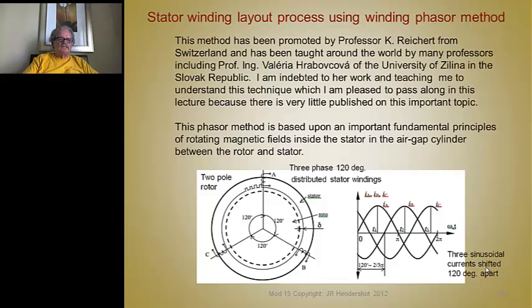I'm really indebted to her work and what she has taught me about how to understand this technique, and I'm certainly pleased to include it in this lecture, because there's very little published on this important topic. And this method is based on the fundamental principles of rotating magnetic fields inside the stator, but we think of that as that rotating field rotating inside the air gap in a cylinder between the rotor and the stator.